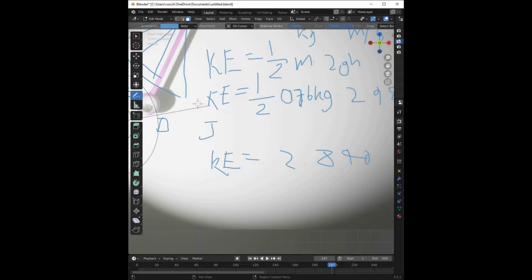So then after that, the cross-sectional area of the impact place is also important, as the result is joules over meters squared that is absorbed. And all of the specimens have 0.0000508 meters squared, which is a small space, because the specimens aren't huge, right? So after that, I can take the amount absorbed.